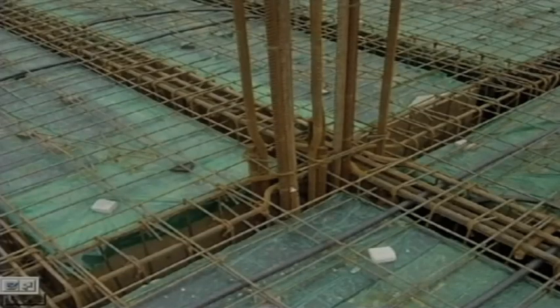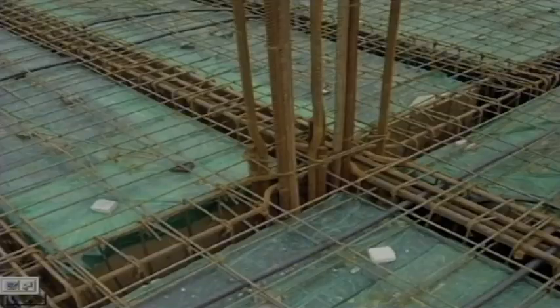So, that is why it is very, very important that you check whether you have sufficient gap and how much the gap will be. If you consider the maximum size of the aggregate to be 20 millimeter, then at least you have to provide 20 millimeter, so that one coarse aggregate can be accommodated within that place. Our code says this in detail, which we shall come to afterwards when we come to detailing.